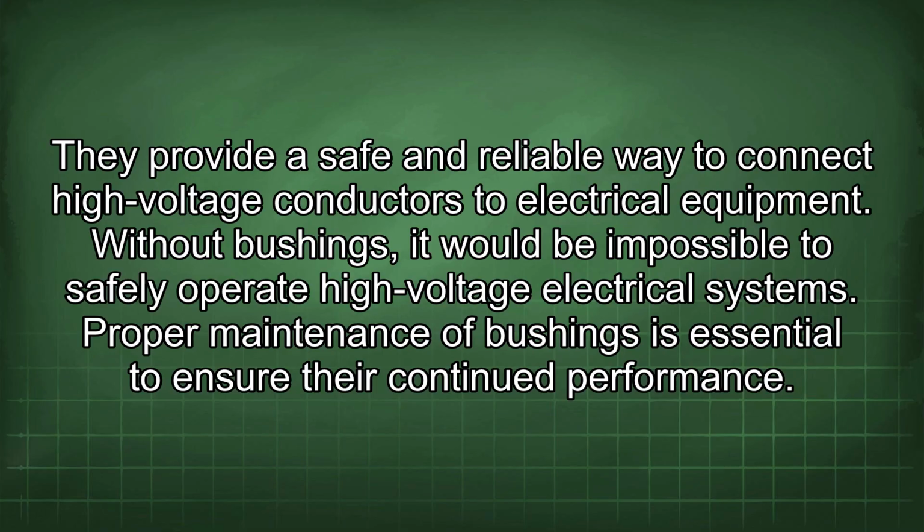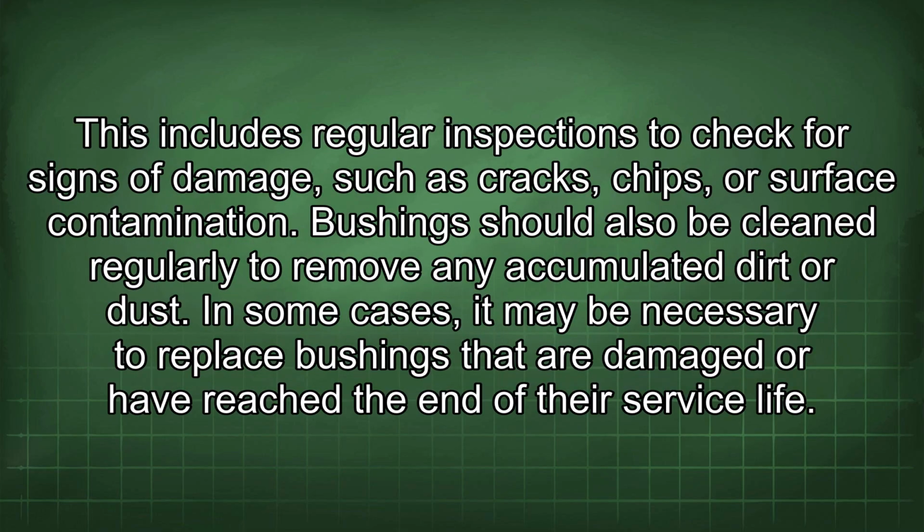Proper maintenance of bushings is essential to ensure their continued performance. This includes regular inspections to check for signs of damage, such as cracks, chips, or surface contamination. Bushings should also be cleaned regularly to remove any accumulated dirt or dust. In some cases, it may be necessary to replace bushings that are damaged or have reached the end of their service life.